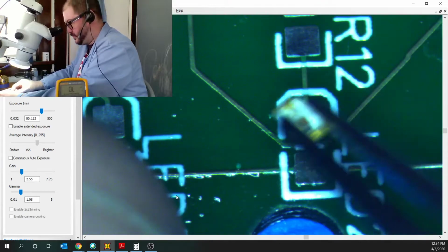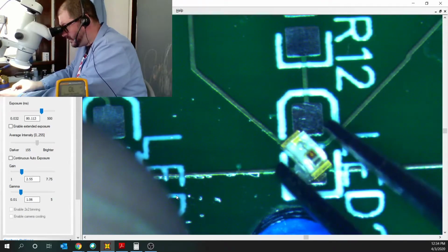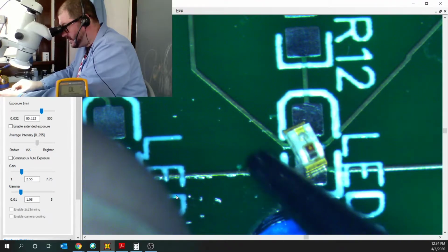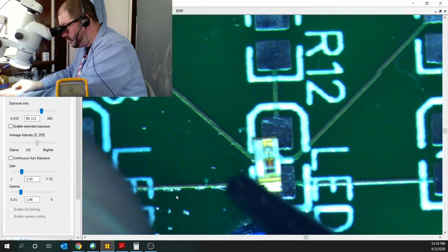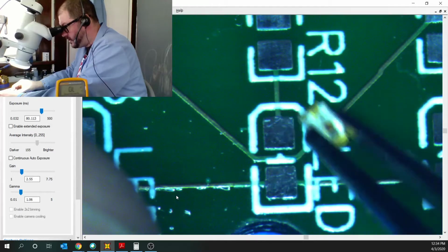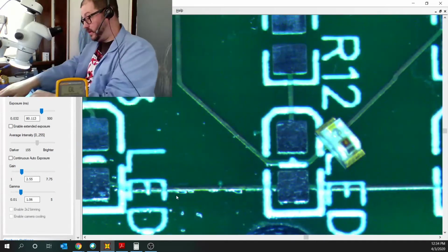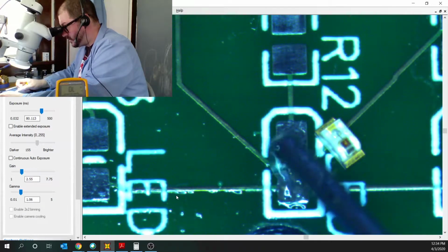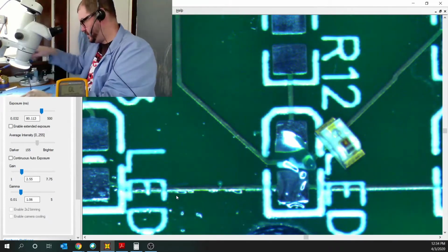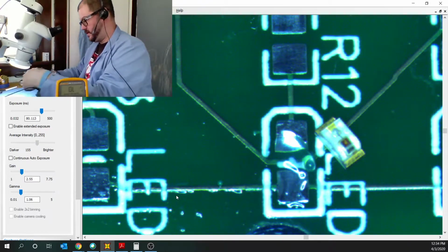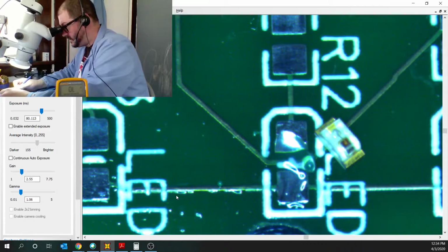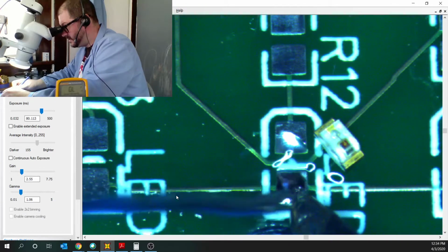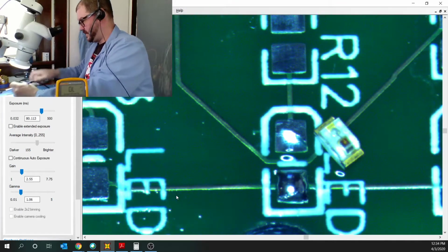So when I flip this back over again, I want the die part of this to be on the bottom side of the board, which is actually what we are going to do right now while we are aware of what the polarity marker is going to be. So just so I keep it fresh, I'm going to put a little bit of some fluxing agent down. I'm going to take my soldering iron and my solder wire. I'm going to tin one of the sides of that guy there.